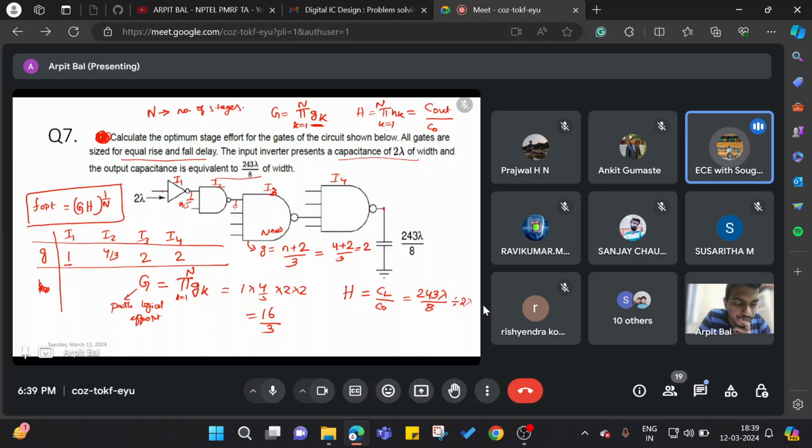So sir, then the total capacitance would be lumped in parallel, they would be adding, right? Yeah. But we are assuming that it is lumped in X1. That X1 is the dominant one. Okay. That means its own output capacitance won't get added.